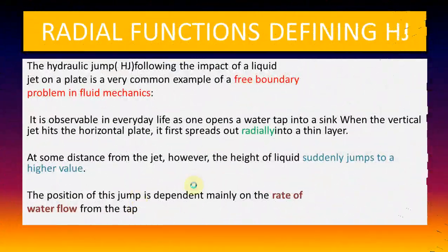First we will discuss the radial function which defines the hydraulic jump, or at what radial distance from the center of the disk the hydraulic jump will be located. The hydraulic jump following the impact of a liquid jet on a plate is a very common example of a free boundary problem in fluid mechanics.